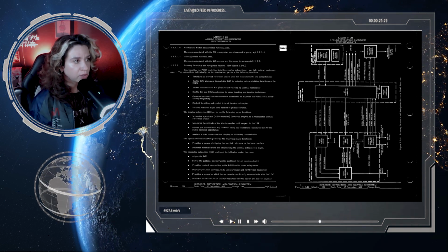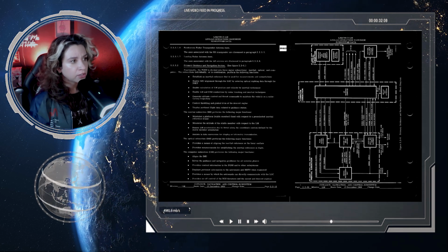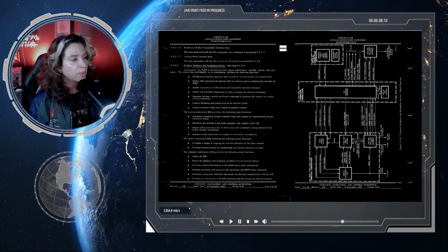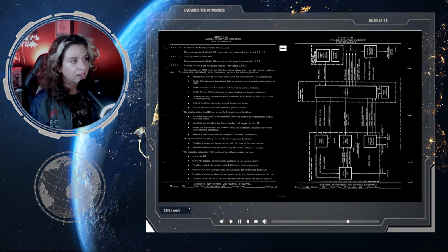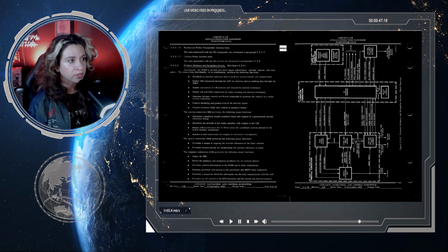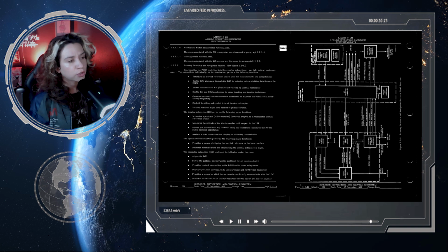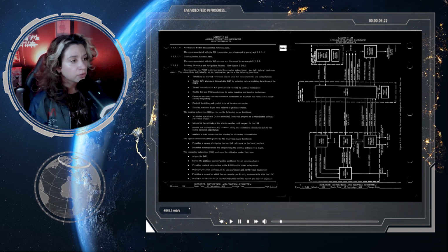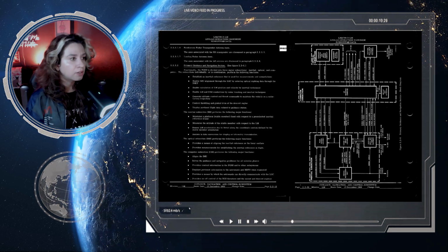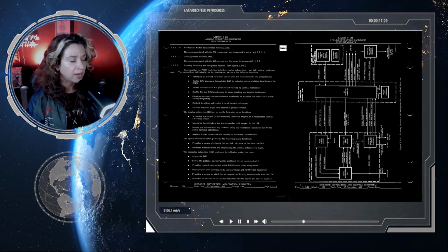The subsections individually or in combination perform the following functions: establish an inertial reference that is used for measurement and computations, enable IMU alignment through the LGC by entering optical sightings data through the DSKY, enable calculations of LM position and velocity by inertial techniques, enable LM and CSM rendezvous by radar tracking and inertial techniques, generate attitude control and thrust commands to maintain the vehicle on a satisfactory trajectory, control throttling and gimbal trim on the descent engine, and display pertinent flight data related to the guidance status.